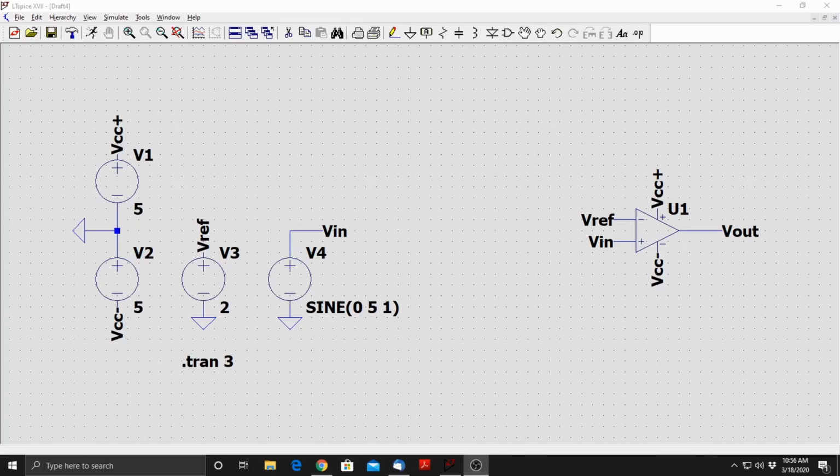At the end of our last class period, we were talking about the behavior of comparators. And we're going to begin today by looking at a simulation for a comparator, the details of which I've already posted on YouTube, but we can quickly review what's going on. So I have a sinusoidal input that is ranging from -5 volts to +5 volts, and it is being applied to the non-inverting input terminal of my op-amp circuit.